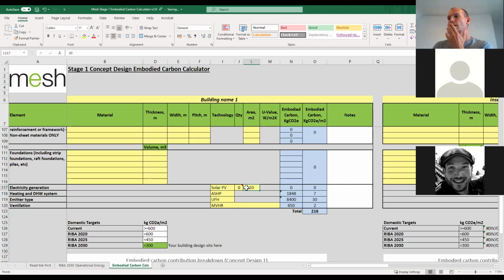In this particular case, we're going to be happy with 4 kilowatt peak that we put in there, being able to pick up the solar. These values will come out fairly high for embodied carbon, and you'll get an appreciation for that. Certainly solar PV, all of this assumes that the building lasts for 60 years and your solar PV system will be changed at least once during that term. So all of those extra costs are built in. Certainly embodied carbon impact is built in.